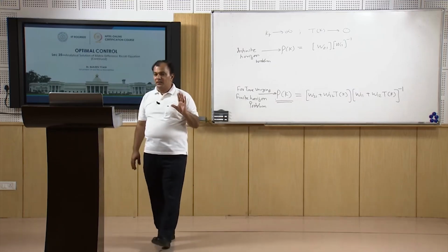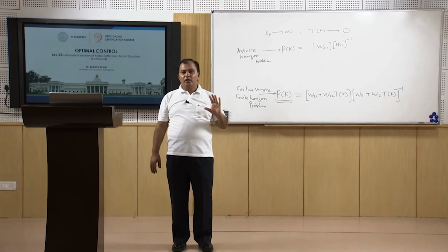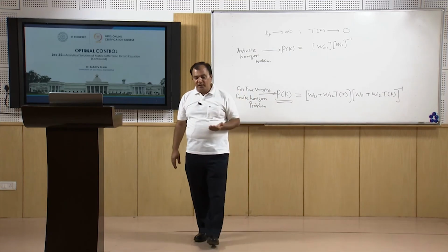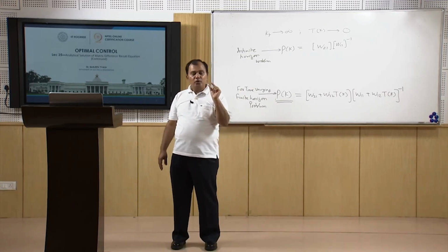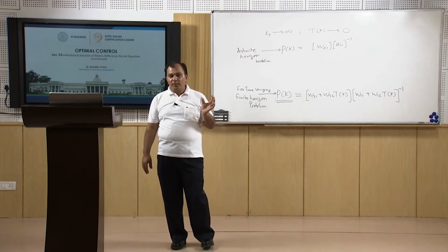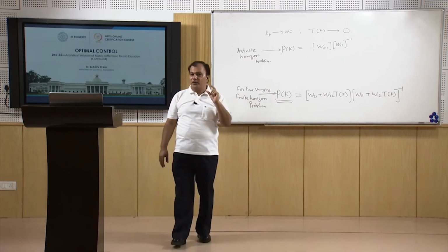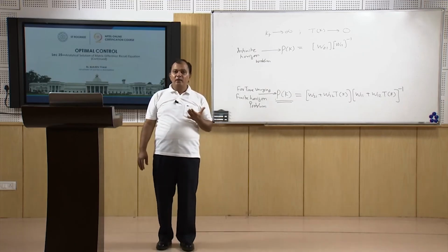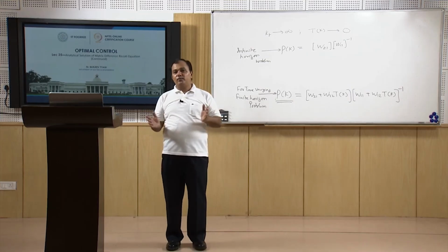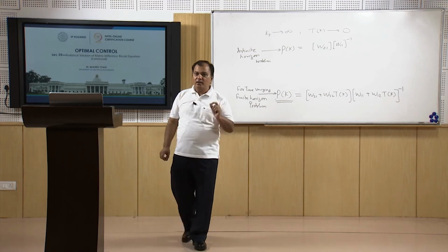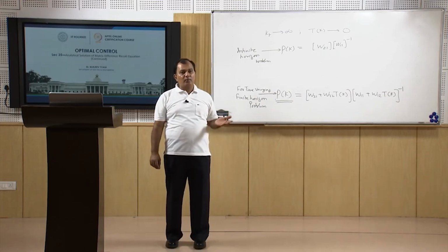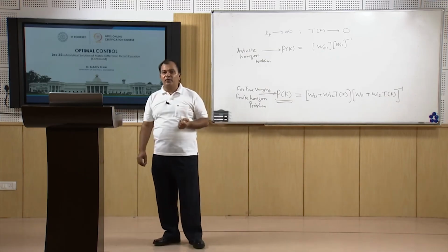Up to this we have discussed how we can use the calculus of variations to solve an optimal control problem. Our approach is, for the given system which is represented in state space, we are trying to find out the optimal value of u which is minimizing a given performance index. In finding the optimal u, we require the Riccati coefficient P to be determined, and P can be determined by the solution of the Riccati equation either in continuous time or in discrete time. And for both the cases we have seen how we can find the solution for the Riccati equation directly in terms of the differential or difference equation, solved by any numerical technique or by some analytical approach. From the next class we start our discussion on dynamic programming.